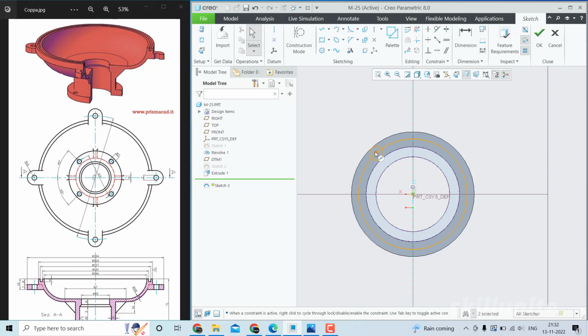So let us create it at an angle, and then we will create an axis line for it, for center purpose. Then you can use this for PCD. For that, just click on the circle, then click on this construction option, so that it will get converted into reference. So now give the PCD. As you can notice, 64 is the PCD, so that means 32 is the radius, so that is fine.